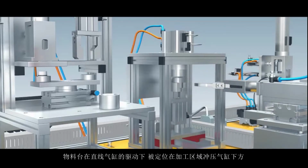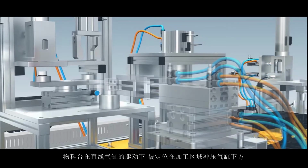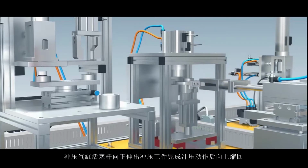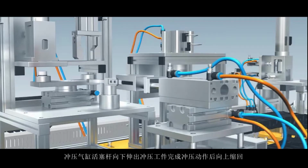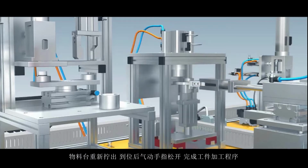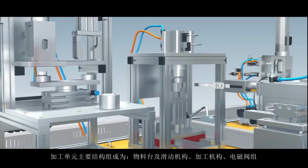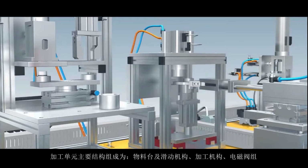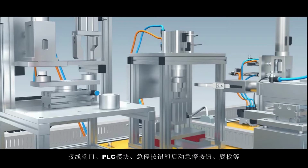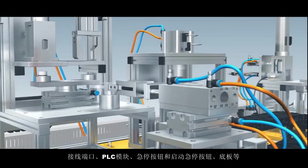The material platform is positioned under the drive of the starting cylinder and is positioned below the punching cylinder of the processing area. The stamping cylinder piston rod pushes down the stamping workpiece to complete the stamping action and then retracts. After the material table is returned, the pneumatic finger is released to complete the workpiece processing procedure. The main structure of the processing unit consists of material table and sliding mechanism, stamping mechanism, solenoid valve group, wiring port, PLC module, emergency stop button and start-stop button, floorboard, etc.